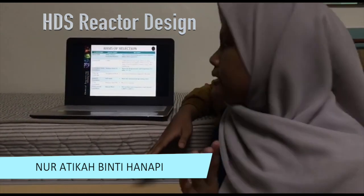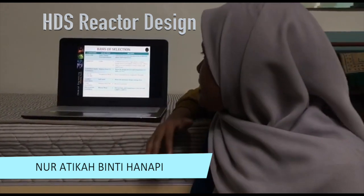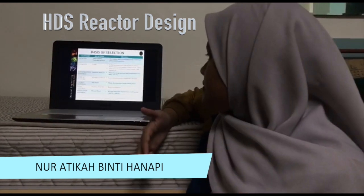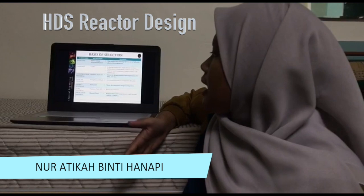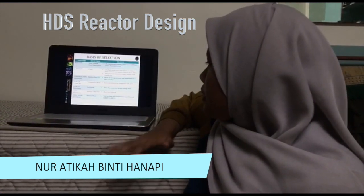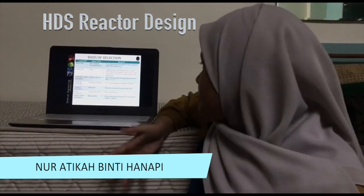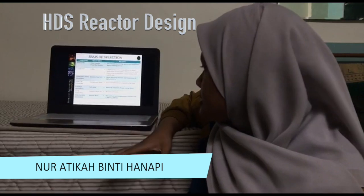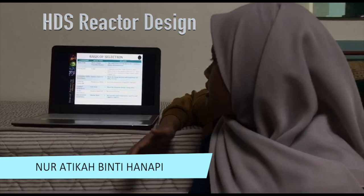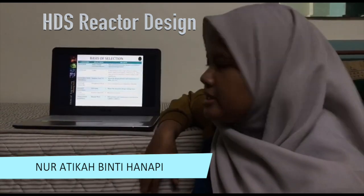This is my basis selection for the reactor. I select a multi-tubular fixed bed reactor. The reason is that the catalyst and the reacting species are in different phases, which is heterogeneous. The catalyst is cobalt molybdenum, because the cobalt promoter has higher affinity to attract sulfur atoms, and the size is 2 mm to maximize the contact surface with naphtha gas. The construction material is stainless steel